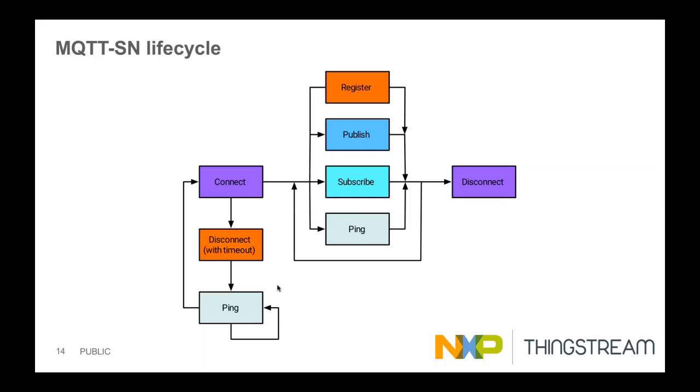So you can then collect them, and then you can go back through the formal cycle of a connect and do all of that stuff, or you can just disconnect again with timeout. So you've got a number of options there that allow you to maintain and manage the life cycle on a battery-powered device and still make sure you don't miss messages that are targeted for you.